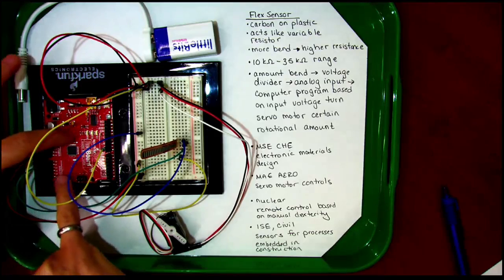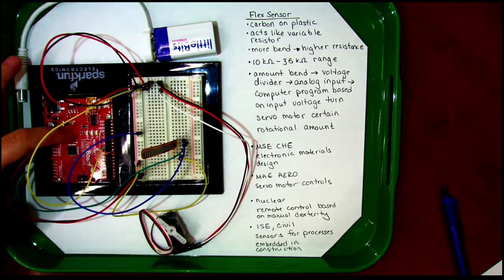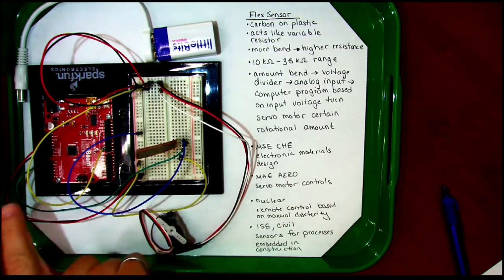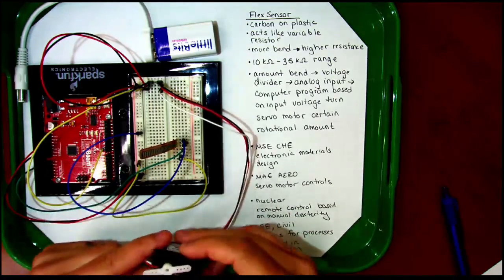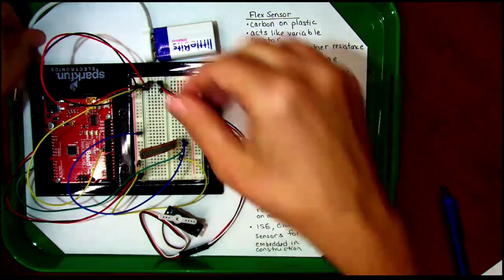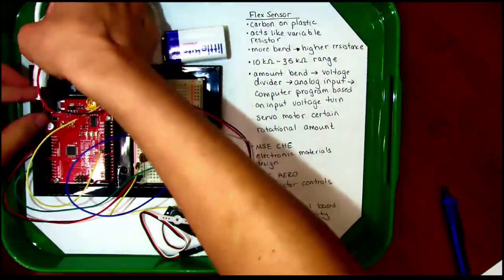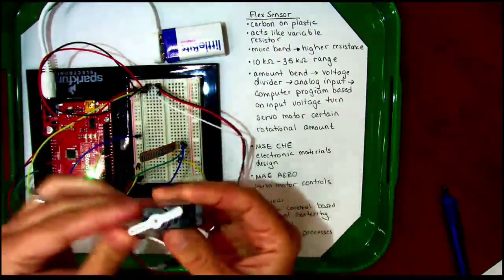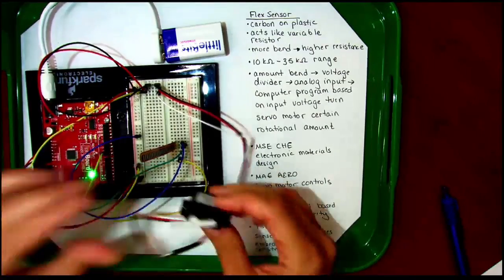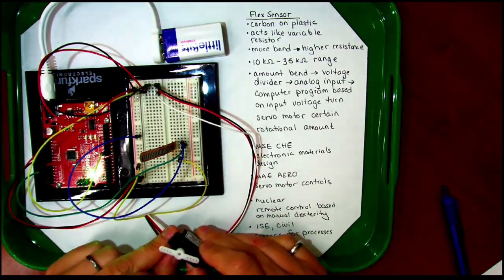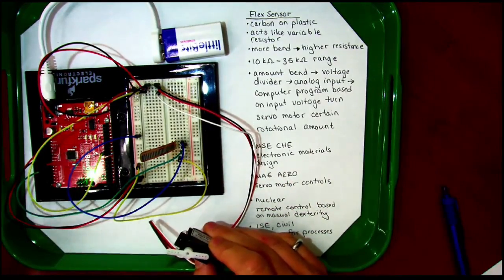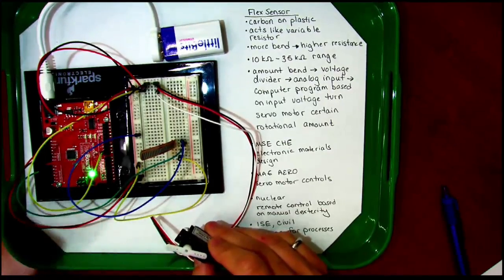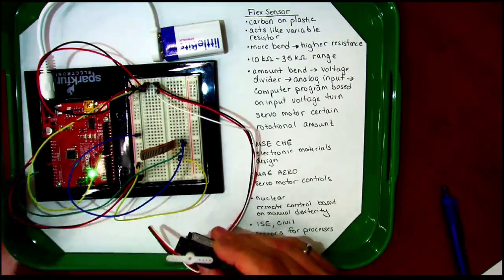The computer card in here then, based on how much voltage is coming to it, sends out a signal to turn a little servo motor some set amount. So I'm going to plug them in, and I'll pass them around when we're done showing it. So again, we have our little servo motor. Remember, servo motors are good for turning small amounts under high torque, very controlled rotations, but only up to 180, some go to 210 degrees of rotation.